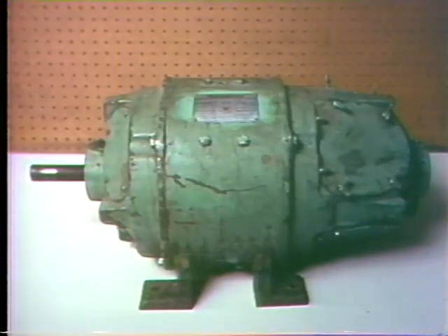Now, the actual amount of difference between the applied EMF and the CEMF is important. It's what controls the current flow through the armature. Well, we've covered two key points on motor action: how the position of the neutral plane is established and the effect of CEMF. And that's about all we have to say about why a motor turns. So let's go on to examine a typical DC motor.